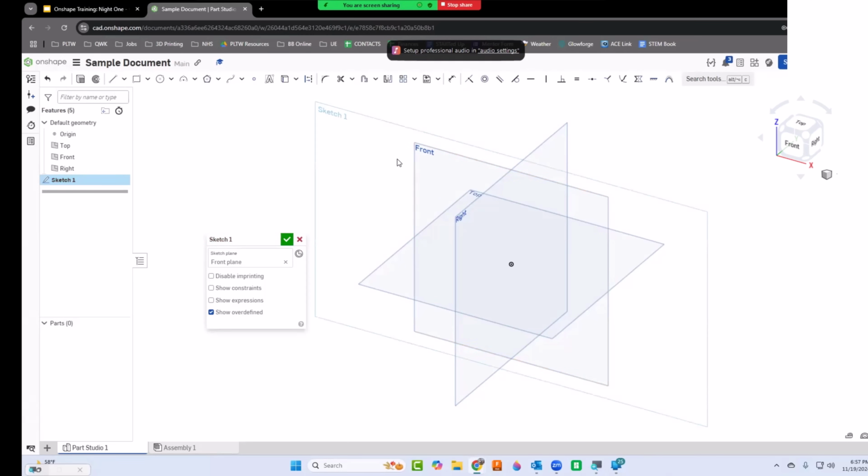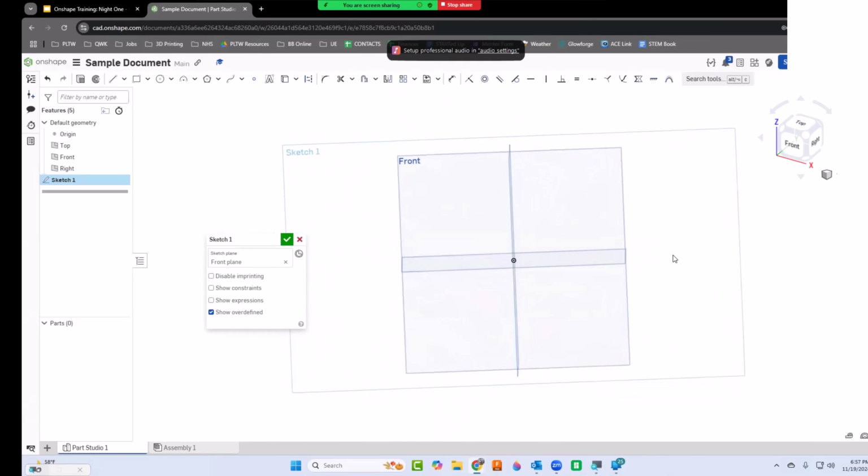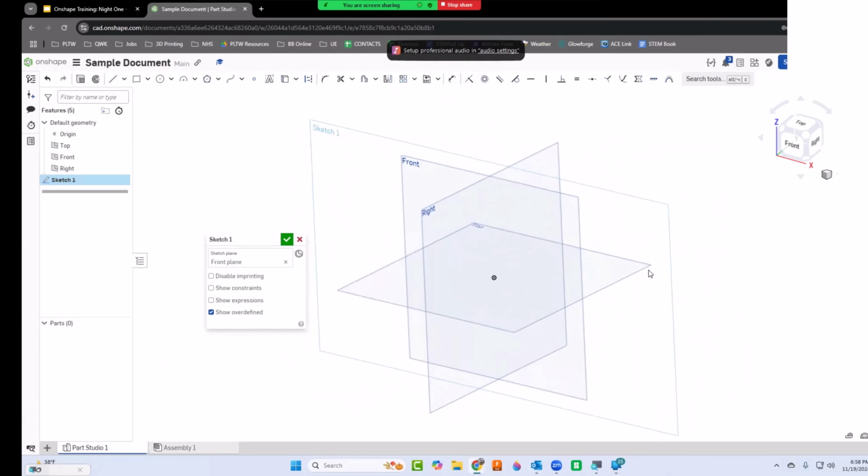So I'll click on it. Now, you're used to probably when you click on that it kind of squares it up and turns it for you. But if you press N, that will normalize it, and that does square it up. Nice thing I love about Onshape, you can hold your right mouse button down and you are in rotate mode. Really, really nice. You got the view cube up here as well.